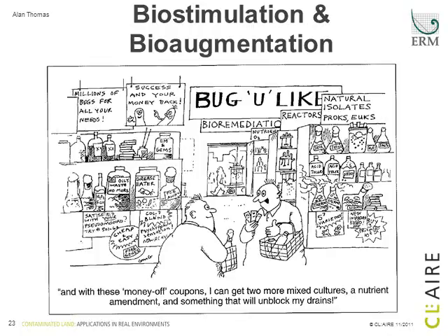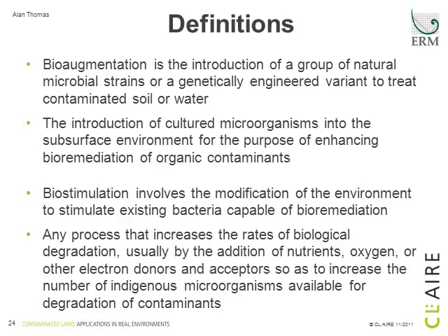I'd like to continue now by looking at the differences between biostimulation and bioaugmentation, as this is often a subject of some debate. Bioaugmentation is essentially the introduction of organisms to the subsurface to undertake remediation, whereas biostimulation is relying on the presence of naturally occurring organisms.